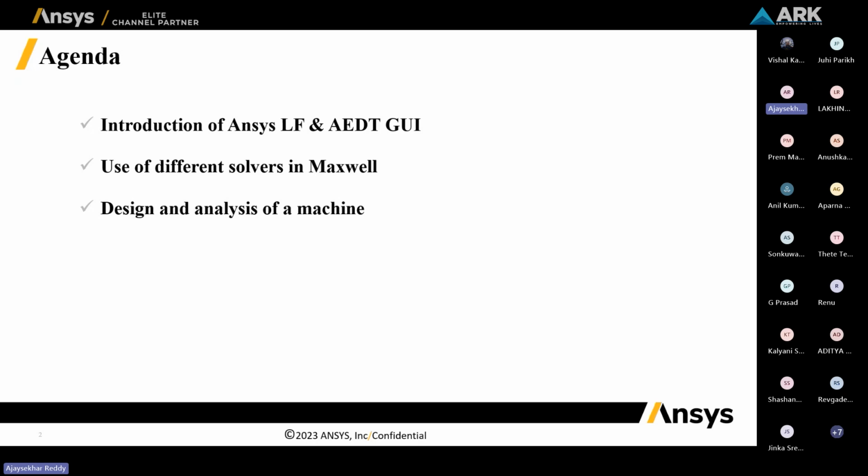One more important part is that for losses, eddy current and core losses, induction machines are a bit important there. In the induction machine rotor side, you have a squirrel cage part, where meshing and these parts are more important to get accurate results.